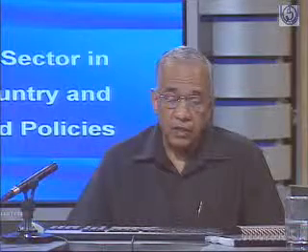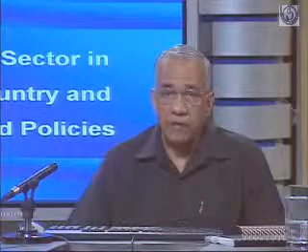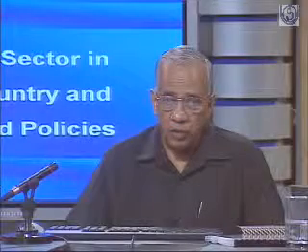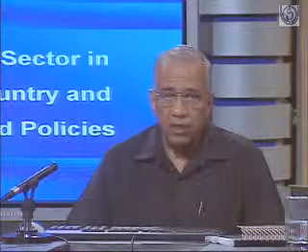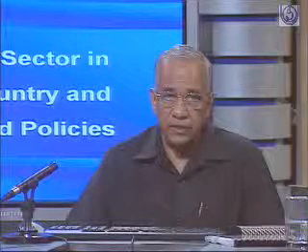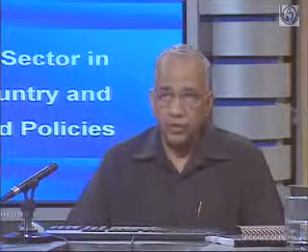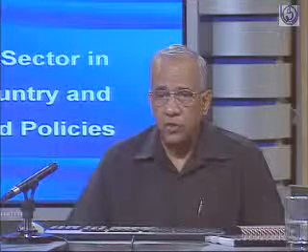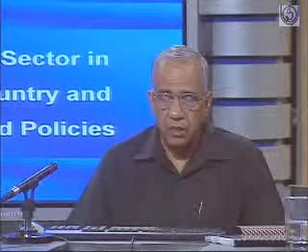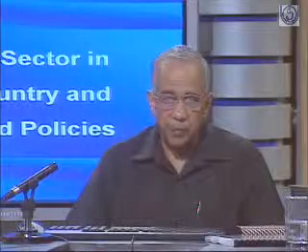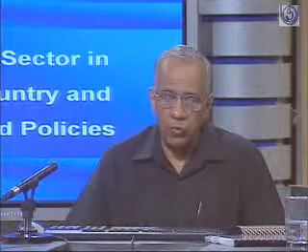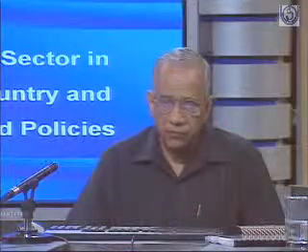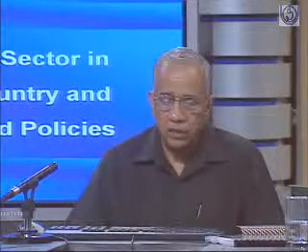These units are the most optimum size of supercritical units in the country. When we say most optimal, it means from the angle of efficiency and from the cost considerations. The 660 megawatt unit was not the optimal size, but we thought that to start with this technology, it is a good size, knowing fully well that this is not the most optimum, but we ventured into a 660 megawatt unit, which now we are slowly changing to 800 megawatt unit size.